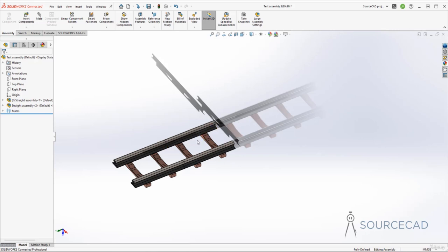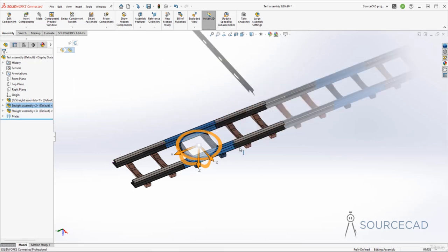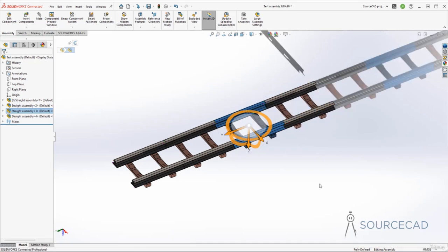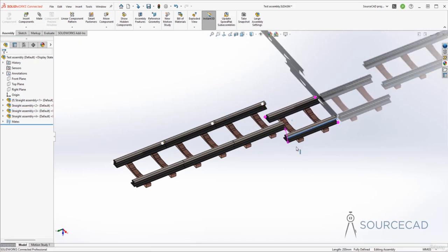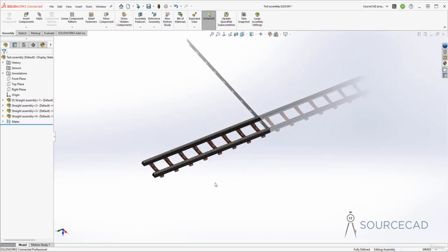Now, to create this copy, I'll simply select this sub-assembly, press and hold Control, and I'll drag and drop it out here. Since there was a connector, it will automatically snap. Let's do it again. Select, drag, and just drop it here. As you can see, once again, we have the connector. So even if I let go here, it will automatically snap. Not only that, you can also move it from here and then maybe snap it to this point. So you can just easily move it around.